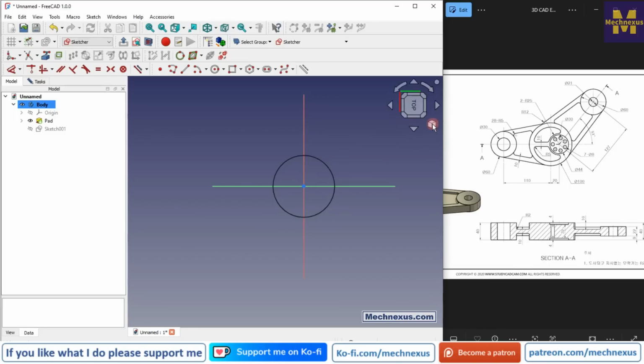Now for right orientation I will go to the isometric view and select this top, and now I will create the profile. First thing we will do is to create two diameters, which will be the construction geometry, and we will first fix that, and after that, this diameter is on the same axis with origin.